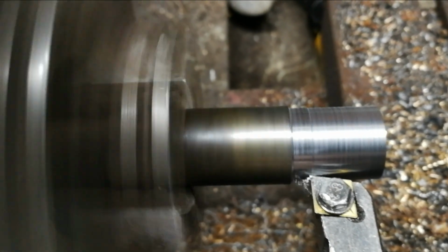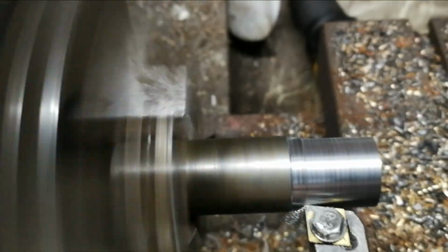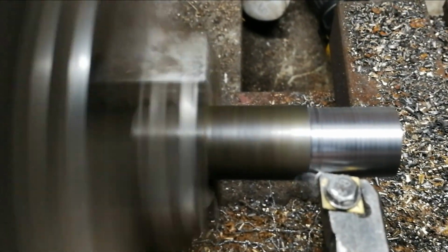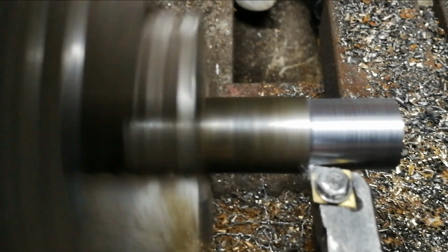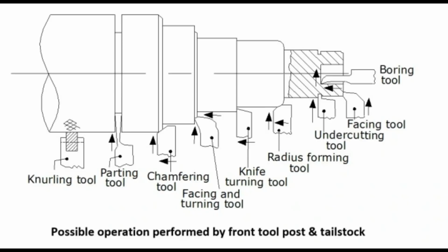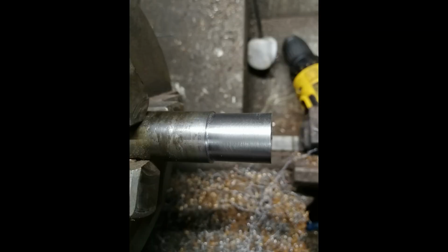Rule of thumb for speeds and feeds is, the larger and harder the material, the slower the spindle RPM is set to. The better the finish requirements or the harder the material, then slower feeds are needed. When reaming holes, the spindle speed should be half of that used for drilling. Forming tool speeds are much lower than standard turning speeds, and depend on the spec of the material.